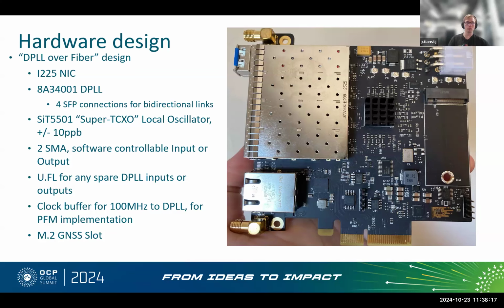If I wanted to build a bigger board, let's say a switch of this design, it would be a different architecture from this. You would have to layer DPLLs, like front IO DPLLs, and then a core one that's the master or something like that. I didn't really want to go into that because that's more of an ecosystem or hardware architecture problem as opposed to a proof of concept architecture problem.